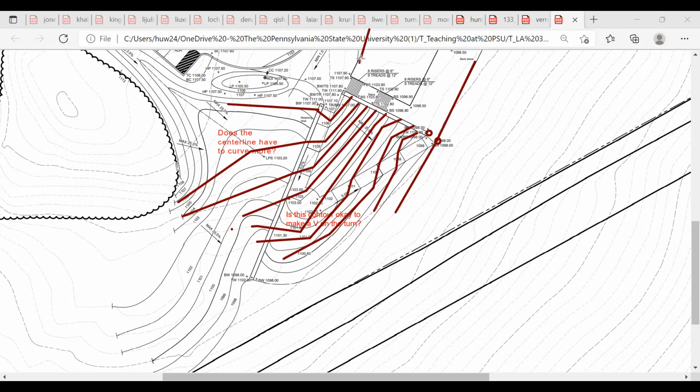So my 8 is over here, and my slope is going like this at 2%. I can use this 2% to calculate what the elevation is of my top ramp. You could start the ramp a little bit earlier, so you could utilize 5%.